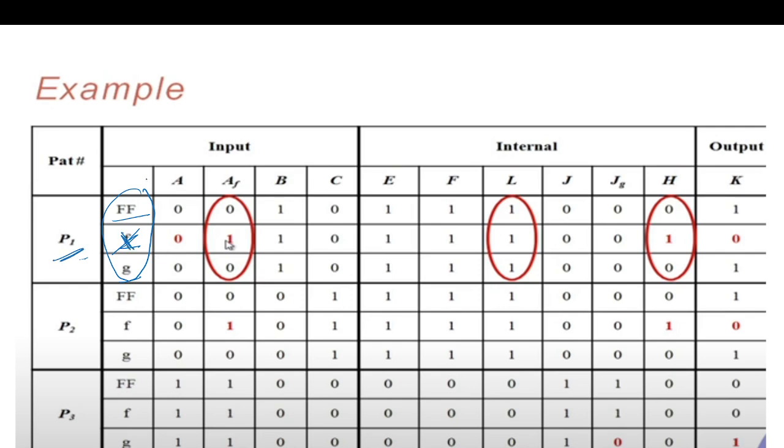We have to complete the whole word, and in this word, even if we drop a fault, its bit position is still going to be evaluated. So we cannot drop the faults unless all of them, F and G, are detected. Then we can drop them and change to the next fault.